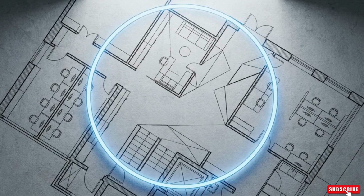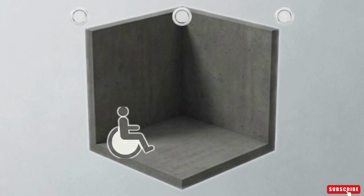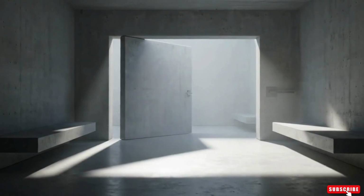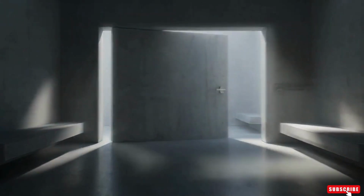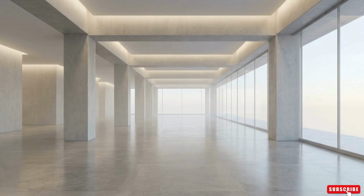Physical kinematics solve only half of the environmental equation. The remaining challenge lies in the complexities of sensory processing. Universal lighting design is a mathematically rigorous component of spatial accessibility. Direct glare and harsh shadowing obscure depth and create false obstacles. Designers eliminate these hazards by implementing soft, diffuse lighting that washes out sharp contrast. Direct glare demands constant pupil dilation and contraction. In aging eyes, this causes immediate sensory overload, disorientation, and visual fatigue. Architects solve this by implementing multi-layered ambient lighting schemes that distribute illumination evenly across all surfaces.